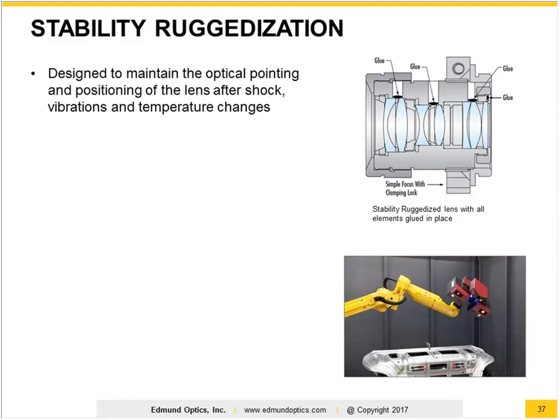Shock and vibe, I think most of us are used to. This is the rattling or the dropping of a system, or it quickly accelerating and decelerating. But temperature change can be an issue as well. As temperatures rise and fall, and this all depends on when things are installed and calibrated versus the high-end temperature it might experience in a factory environment, you might see a 10, 20, 30, 50 C change in the system. That can be critical to the actual alignment of things.